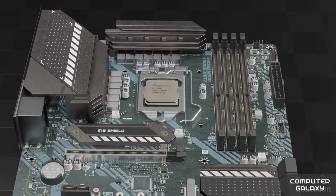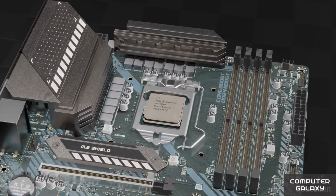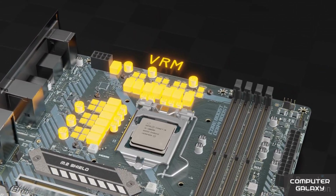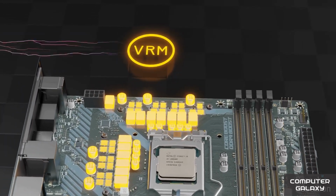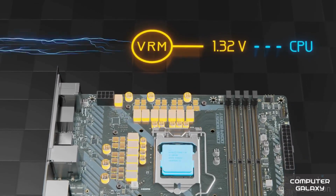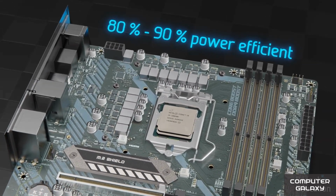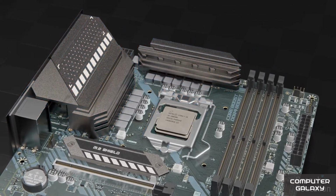Let's move on and skip over the many different sockets and connectors throughout the motherboard and focus on the voltage regulator module, or VRM, found near the CPU. These components are used to drop the voltage coming from the power supply down to the 1.3 volts used by the CPU. As a result of all the power flowing through these components and their 80 to 90% efficiency, heat sinks need to be placed on top.